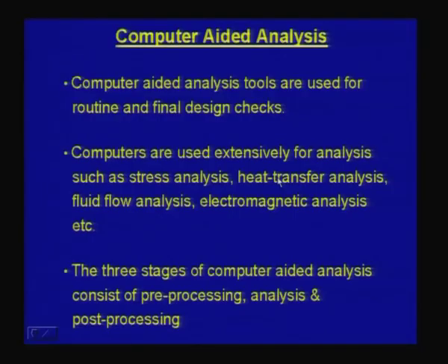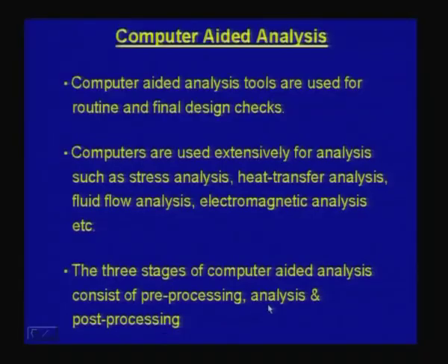So, the analysis is not restricted to purely a stress analysis. As a part of mechanical design, one may do a heat transfer analysis, or there are many mechanical components where the design requires a fluid flow analysis, and a few components where one has to do an electromagnetic analysis in order to design a product. And computers have been used at all three stages of an analysis. For example, if I take a finite element analysis package, which can do a stress analysis or a heat transfer analysis, the computers can be used for pre-processing, analysis and post-processing.